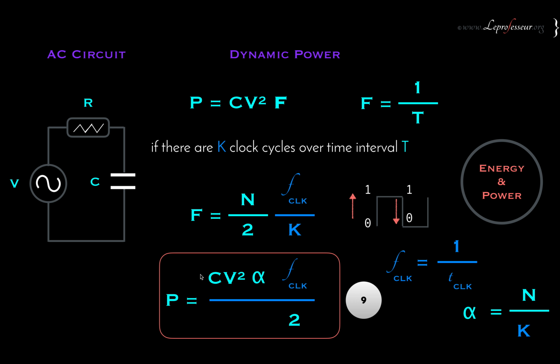Different EDA tools can extract that information, which is needed for other tools as well, let's say timing analysis, PrimeTime, to reflect the true or close to true value. In this whole equation, there is no resistance term. Interesting. So we are only dealing with the capacitance, the voltage, the activity factor, and the clock frequency. That will give us the dynamic power.